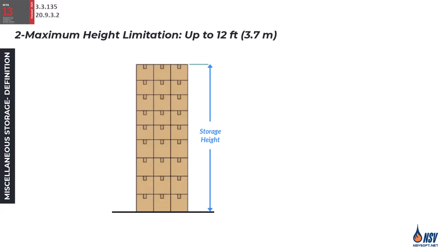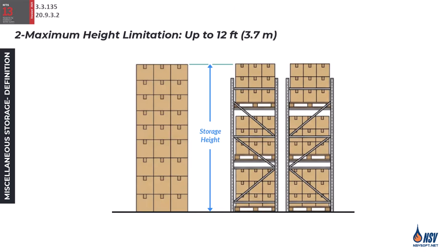It is important to note how we apply this to rack storage. We shouldn't only account for the height of the highest part of the rack structure itself. Instead, we must also consider the height of the load sitting on that top level. Our true storage height is defined by the very top of the highest stored item, not just the metal framing.